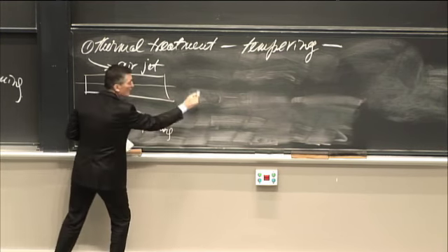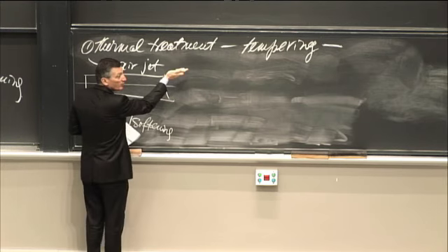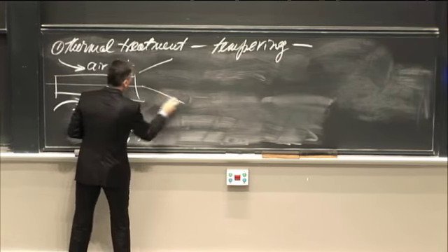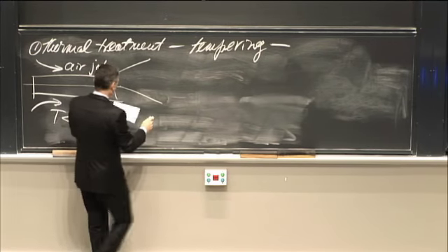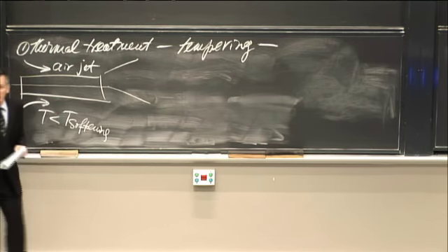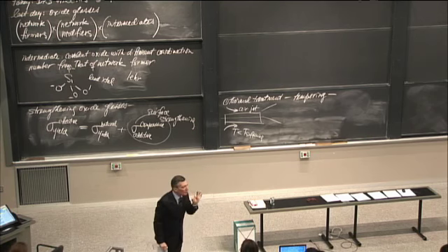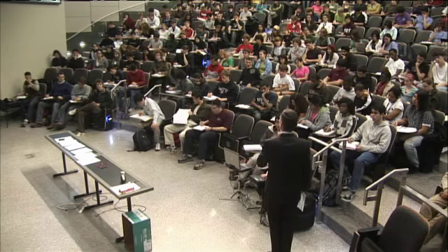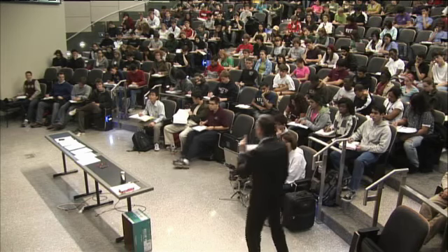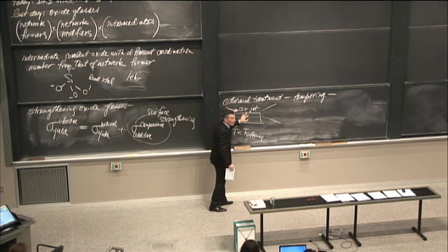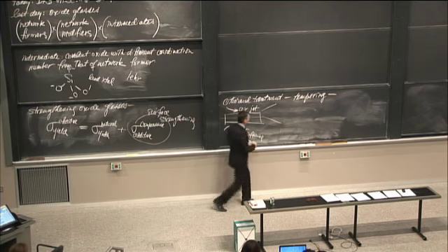So I'm going to cut this piece of glass in half, and I'm just going to look at the upper surface. The same thing happens on the lower surface. So let's now blow this up. I'm just going to look at the upper half, and I'm going to divide it into two zones. This is the first level, most primitive finite element analysis. I'm going to divide it in two, and I'm going to say this has two zones, two cooling zones.